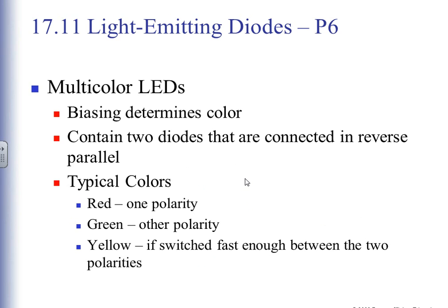So here's an application where I have a current limiting resistor preventing my diode from turning on. I could have a multicolor light emitting diode. And so we just said that the light of the light emitting diode is based on the color of the plastic, right? And now I'm telling you that I've got 3 different leads. So this diode will have 4 leads. 1, 2, 3 anodes and a cathode, and depending on which lead is energized will give me the color I want. In this particular case, the plastic didn't change color.